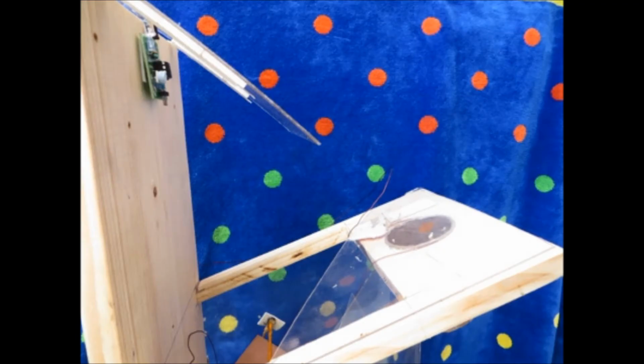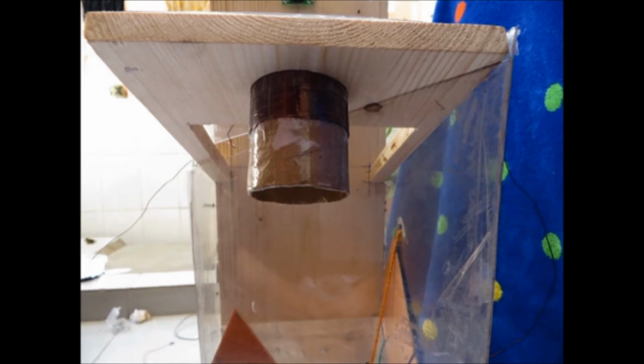The top of the segregator has an inclined flap for the waste to drop down. An IR sensor indicates the arrival of waste. The second stage is the wooden incline, which houses the LDC 1000 and the inductive coil. This system is used for the detection of metallic waste.